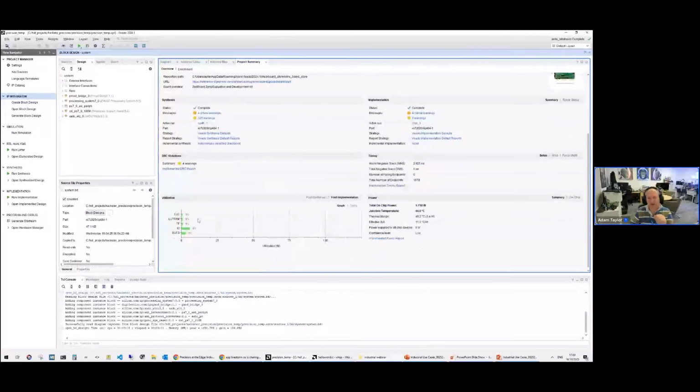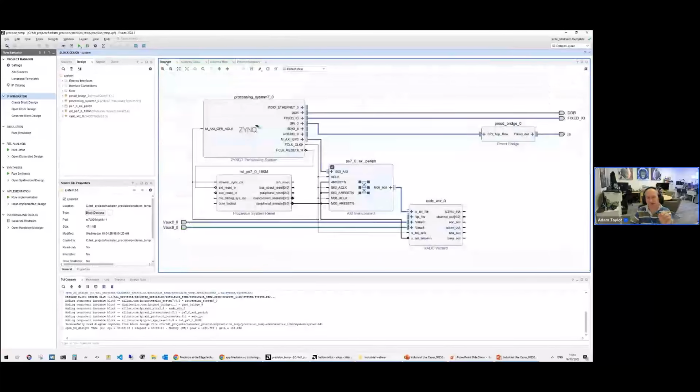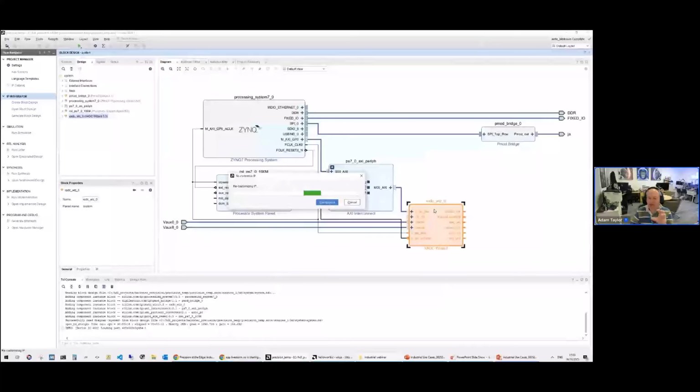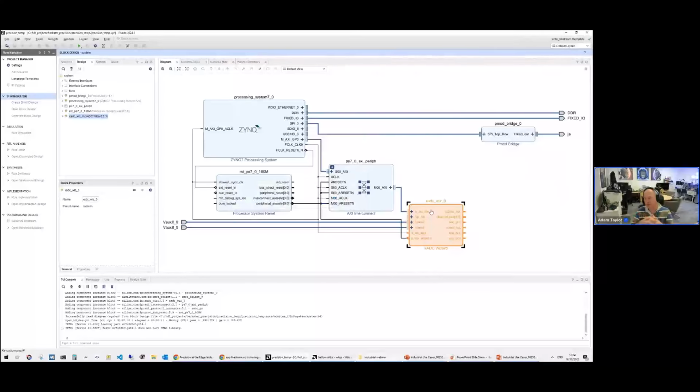We're not using a huge amount of the FPGA, but if we come back to our block design, the main important thing that I want to share is how the XADC is configured, because that's really quite important for us all. So let's just reconfigure that, recustomize that, and then we'll take a look at this as it goes through. But that XADC, like I say, it's really important to be able to give us that sampling of the external values.